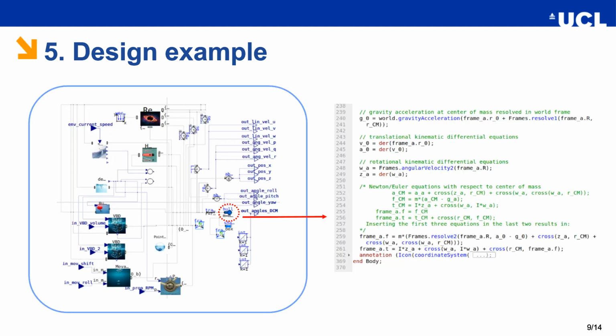The first element in the model of the blended wing glider is the wet hull, highlighted in the red dashed circle. The hull model implements the dynamics of a rigid body, so including the nonlinear effects such as Coriolis and centripetal effects, and the added mass. The model can be instantiated just by dragging and dropping a dedicated icon and connected to the other elements of the vehicle by means of specific connections. The actual code is embedded in a dedicated interface, which we will further see later on.